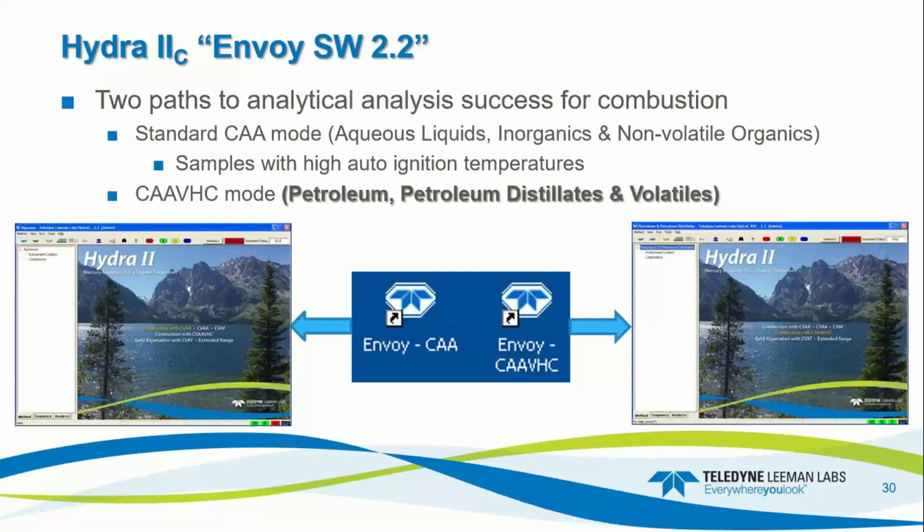The samples are readied beside the injection port, and when that temperature reaches a preset degrees in centigrade, the sample is going to be injected into the combustion zone. What this will do is inadvertently stop the sample from going through its auto ignition, for the ones that are low temperature, let's say less than 100 degrees C. So it won't explode or combust outside the combustion zone, losing the sample.